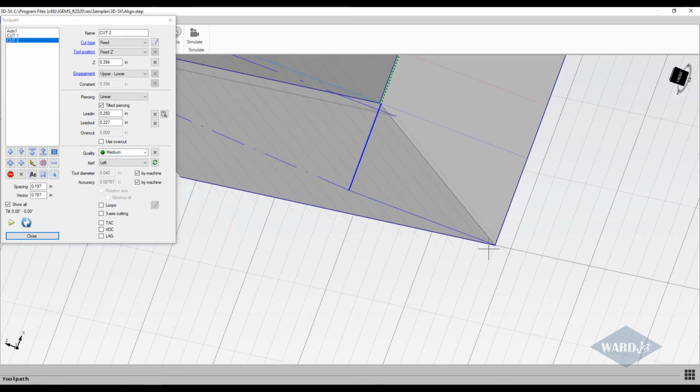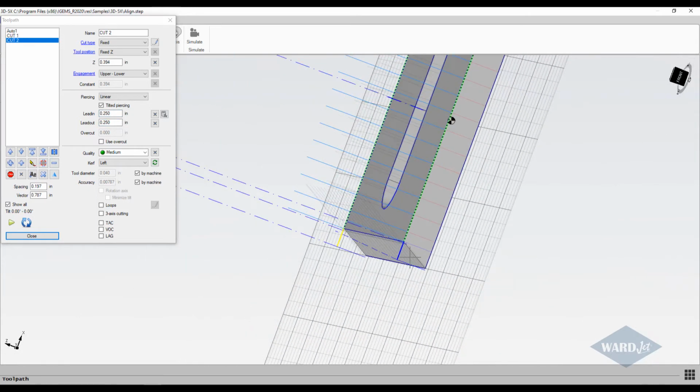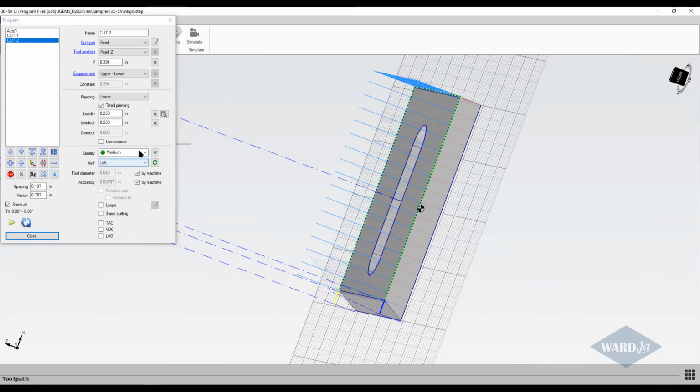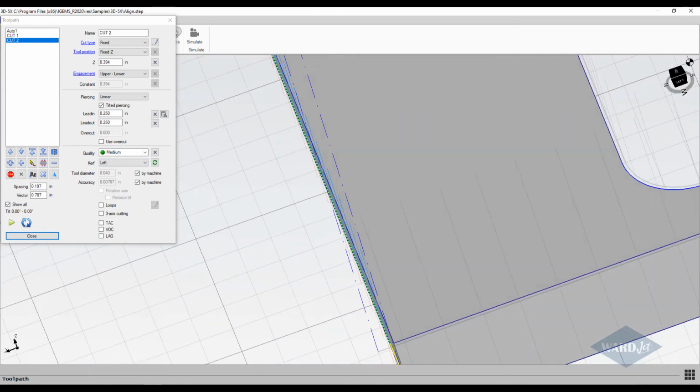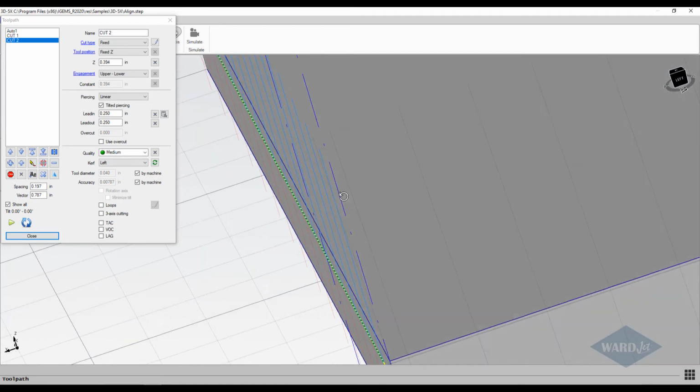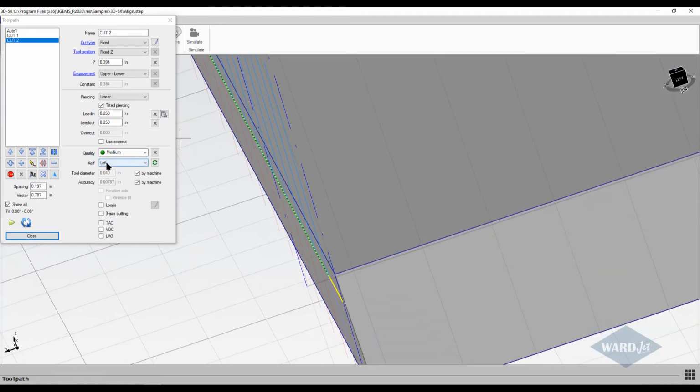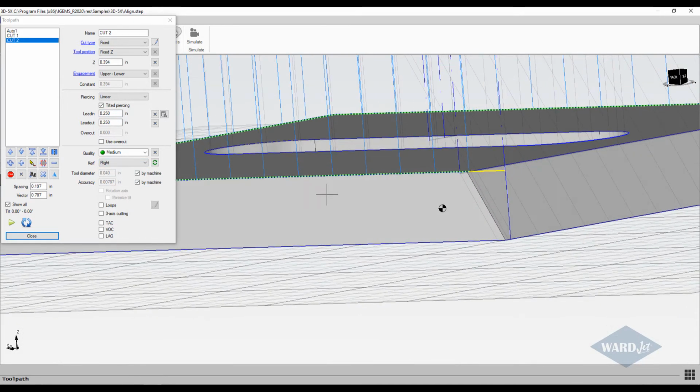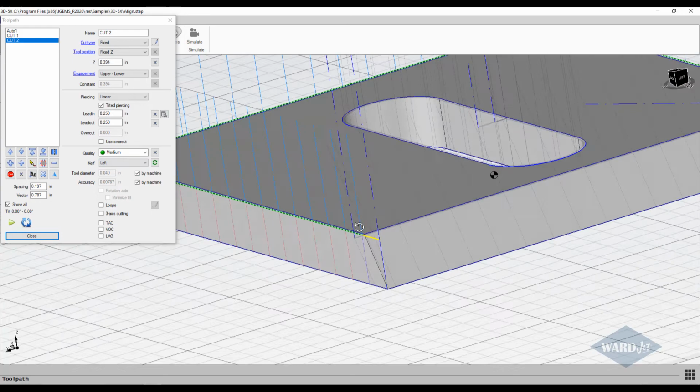And if I want to make sure that the lead out is going to get beyond there, I can add a little bit to that. We'll make it 1/4 inch also. And when you do a cut like that, you just have to make sure that the kerf is on the appropriate side. Since we're going clockwise around that outside cut, we want to make sure that that is set to left, which it is. If it were set on the wrong side, you wouldn't see the red lines indicating the stream trajectory, but you can just click into here and change it to the appropriate side.